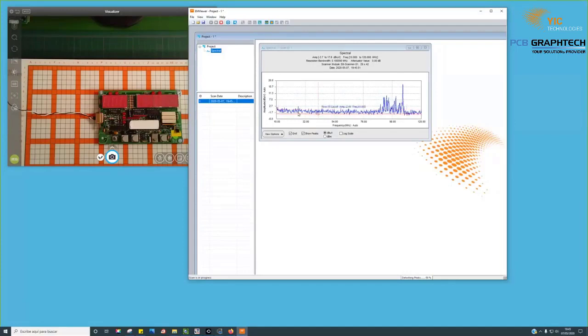You can see that from 10 megahertz to 120 megahertz, I have activity only in this area, that is the area of FM broadcasting, with this kind of levels. Later we will see what these levels are. Obviously, if you make these measurements in some kind of shielded structure, you will have more possibilities to reduce this noise from the environment. And look at this, the system is measuring the biggest peaks, four in this case.